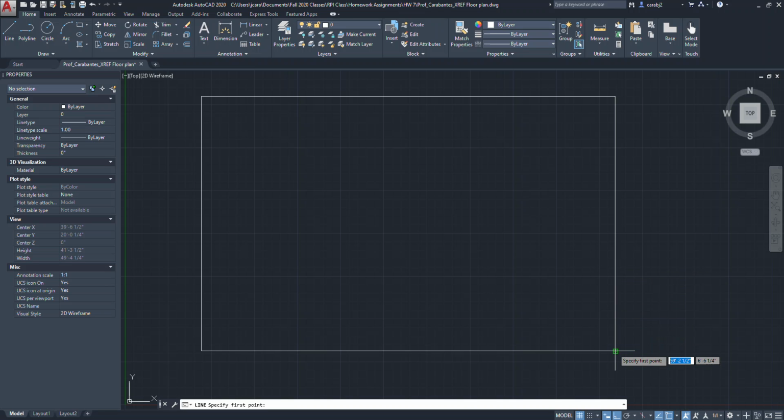So we're going to draw a line up this way in this direction. We're going to draw it at 15 feet. So you're going to hover over the endpoint, go upwards, and type in 15. And remember feet with the little apostrophe down in your keyboard by the enter symbol.